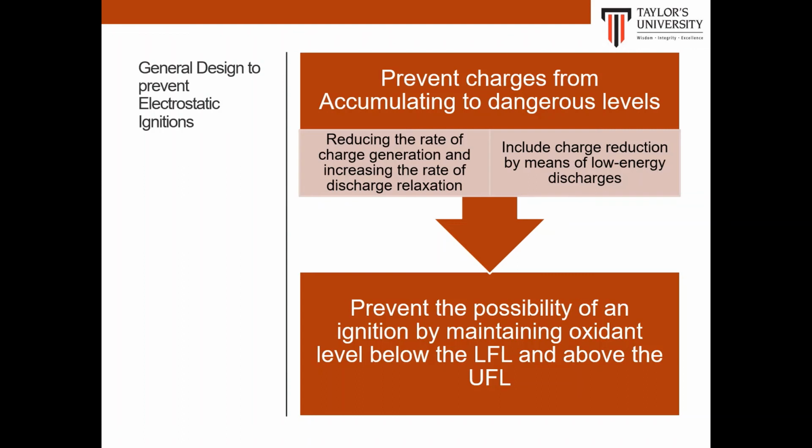These methods are used to achieve this objective by preventing charges from accumulating to dangerous levels, by first reducing the rate of charge generation and increasing the rate of charge relaxation. This method is generally used when handling liquid. The other one is by designing the system to include charge reduction by means of low energy discharge. This method is generally used when handling powder.